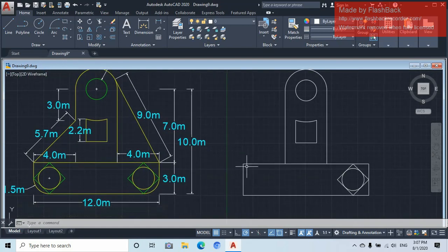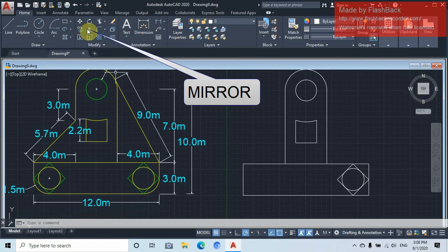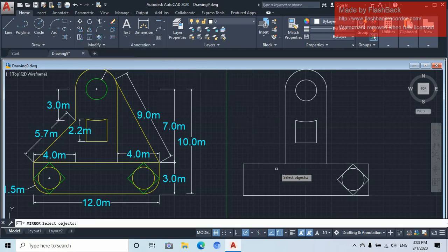You'll see that we have the same object this other way. So how do we do it? Do we still go through the same stress? No, we go now to the mirror, the mirror image, or the mirror tool. To have a mirror image, you left click on the mirror tool, then you come here. We select the object. Let's keep our cursor somewhere here. You left click to select, then you bring it over. There you are, you covered it all.